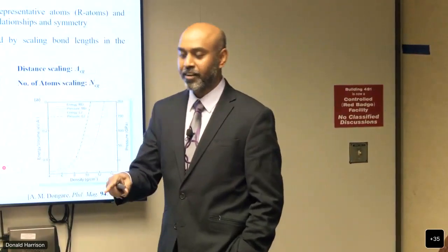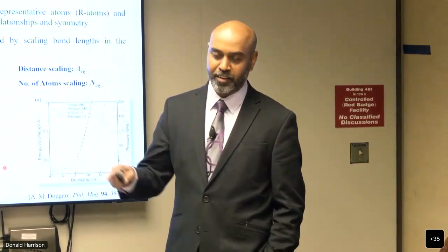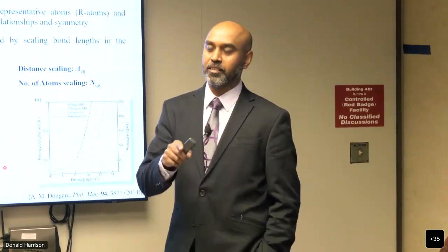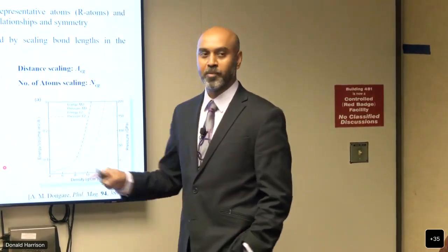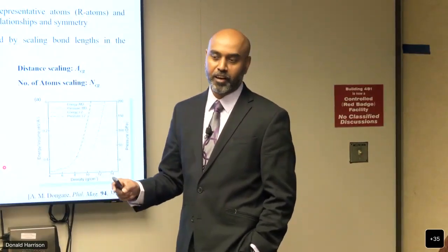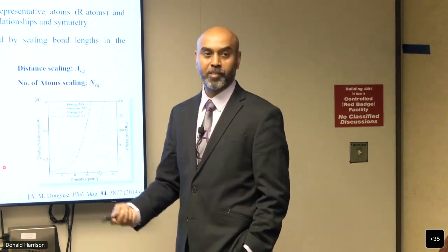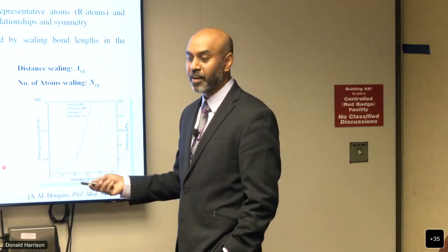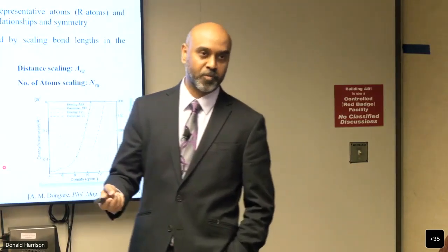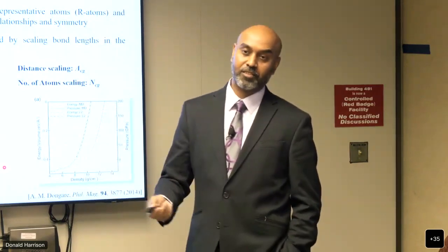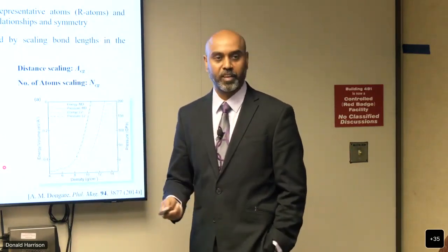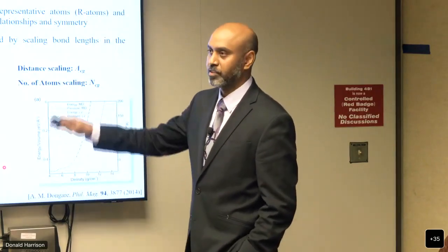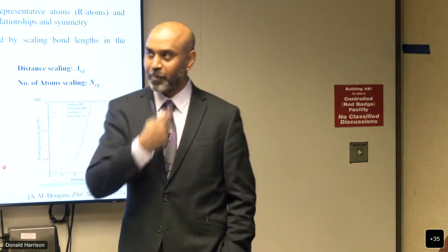Well, we have added, not in this work, but we have added dislocations to single crystals to look at the effect of dislocation density on the decay of the shock wave as it travels through the material. So that allows us to see how a shock wave interacts with pre-existing dislocations, and we observe that the decay is much faster in those, and it modifies the dynamics as well. It also actually strengthens the material in a certain way in terms of void nucleation and damage evolution, but not in this scope of work.